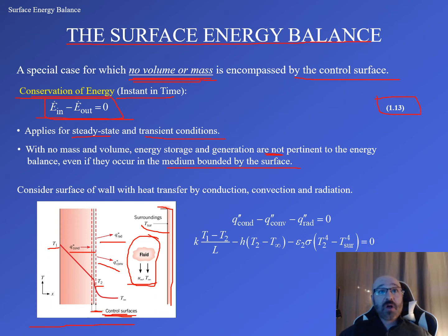So considering all of this, by conduction, convection, and radiation, we have the following relationship as related to the variables that we see in our given diagram on the left, that our heat flux for conduction minus our heat flux for convection minus the heat flux for radiation is equal to 0. So then we can start plugging in, and we can say, okay, well, I have relationships for conduction, convection, and radiation heat flux.